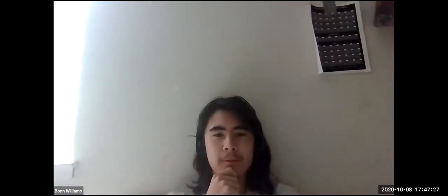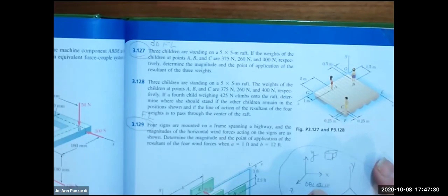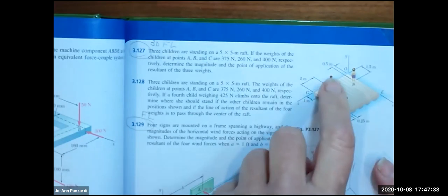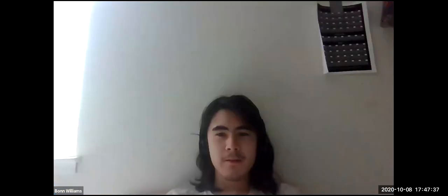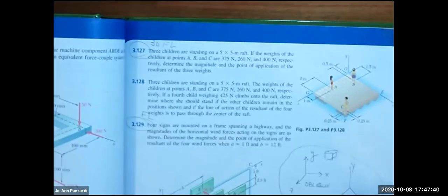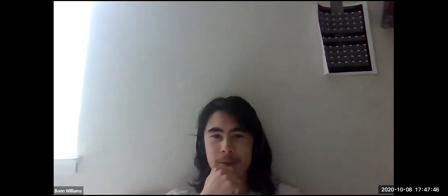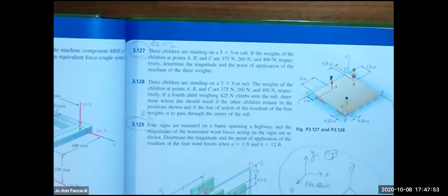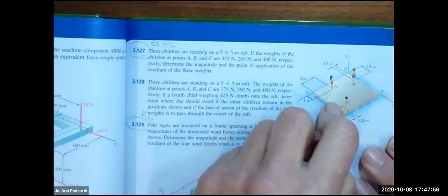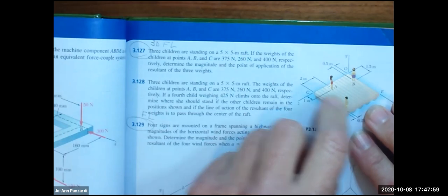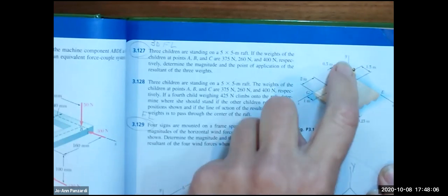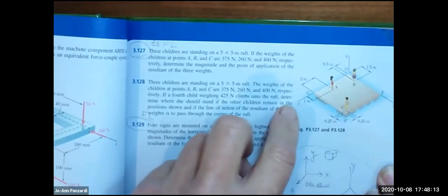So is this a force moment or a force location problem? Force location. Correct. So what's the first thing I have to do? Find the resultant force, which in the end is going to be what? You would have to add up the weights of all three of the children, three weights going down. And now I have to find the resultant moment, right, in both these problems. So, Myra, do these kids create a moment about the y-axis? No, because they're parallel. Correct. Do they create a moment about the z?